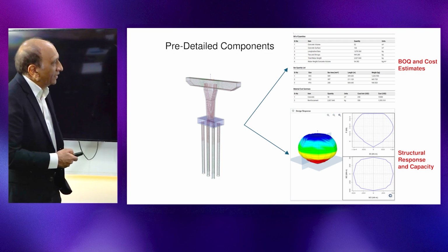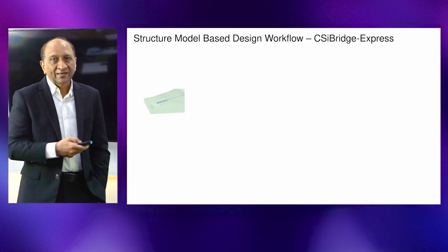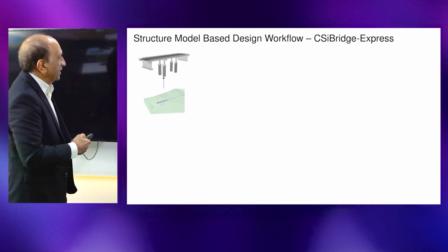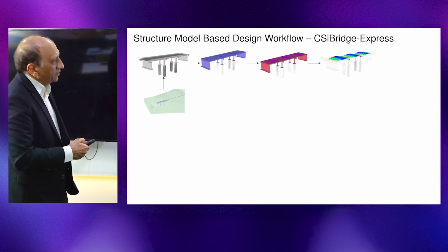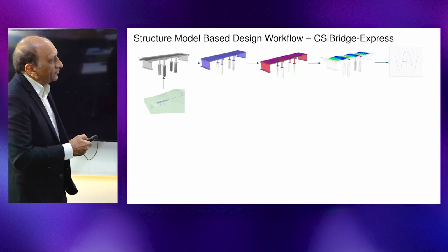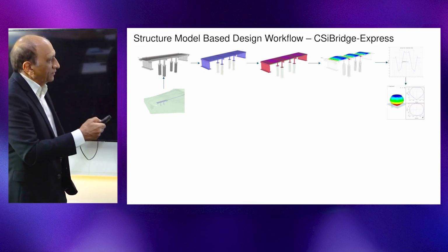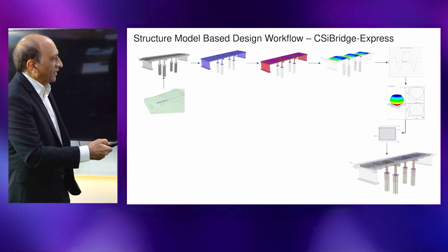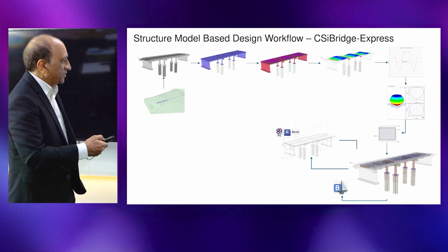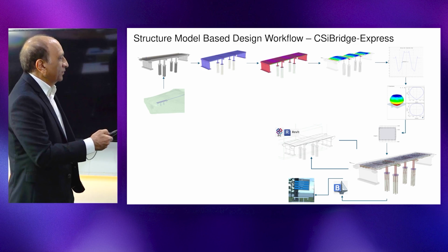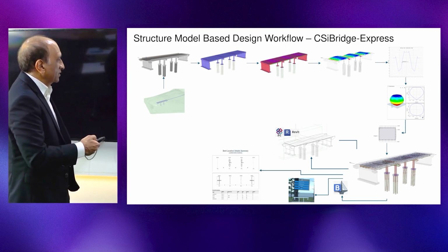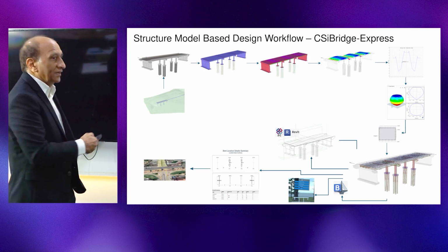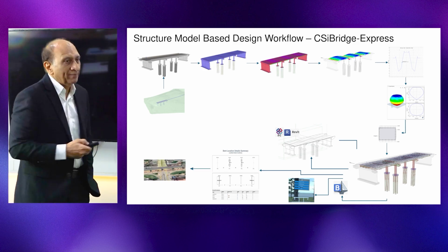And if I expand that into a full workflow for the bridge, then it can start from the site, from the Google map, you put the bridge there, you get the parametric model, and then you go to the analysis, you go to the design. We can do all of that workflow, we can calculate the capacity, we get the section, we get the final reinforcement, we go to Revit or IFC, transfer it to the BIM or with virtual reality, and then you can get the cost estimates, we can get the BOQs and done. And you can then get the final report and then put it back onto the Google map to complete the cycle.